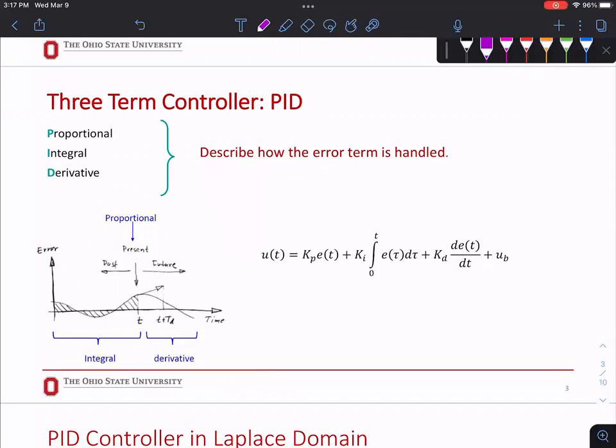The root locus is more of a design tool to give you ideas how pole and zero impact the response of a system. The lead lag compensator, you usually don't actually design a lead or lag compensator, but because it looks at the frequency response, the Bode plot, gain and phase, if you are looking at the frequency response of your system, you're able to design a controller that will fix it. So you can design the controller in your frequency domain rather than the time domain or S domain. All right, so we'll see how far we can get, but that's my goal, to walk you through all 3 methods.